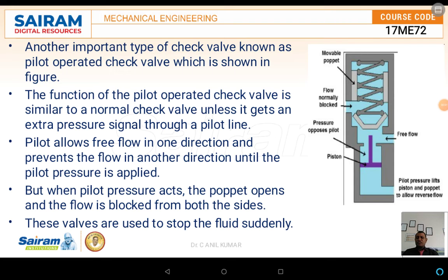Hello everyone. In this session, we will discuss another important type of check valve, which is known as the pilot operated check valve. The schematic diagram shows the pilot operated check valve. Here, it consists of the free flow opening, another one is a pilot, and another one is the flow normally blocked.